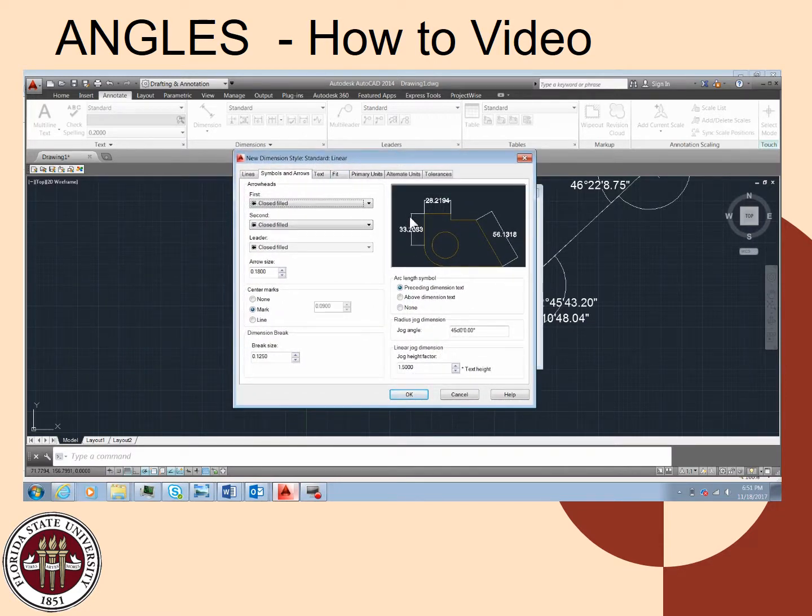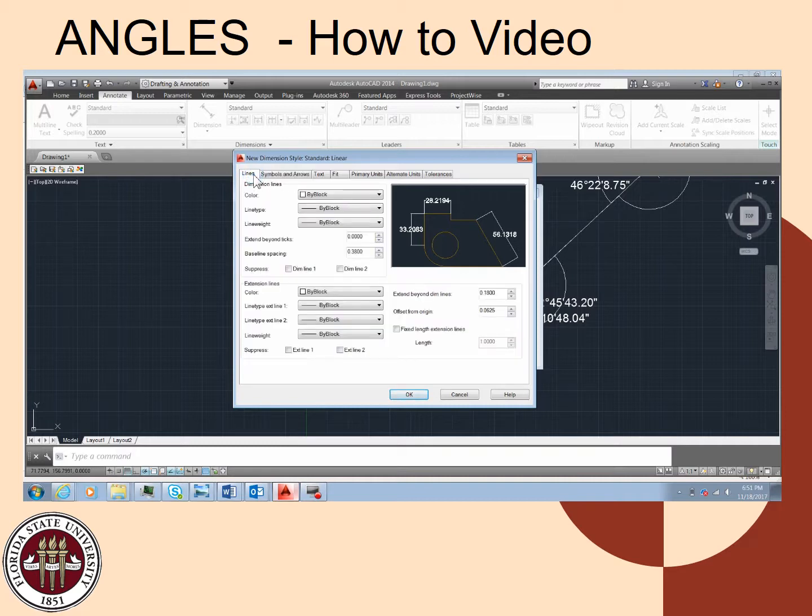Now I don't want these leaders and the witnesses to appear, so I'm going to turn off the ends. Also, notice they're still there, so I'm going to turn off the dimension lines and the witness lines.